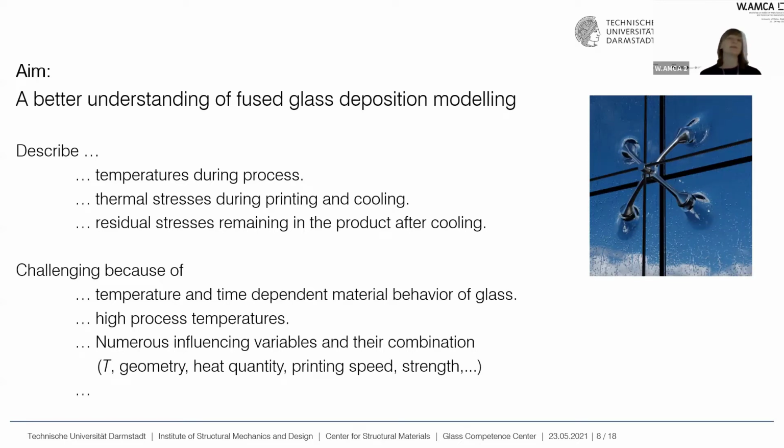And I would like to describe the temperatures during the process, the thermal stresses during the process, and printing and cooling, and also the residual stresses which remain after printing. This is challenging because we have a temperature and time dependent material behavior, and we have very high process temperatures. And of course, we have numerous influencing variables.